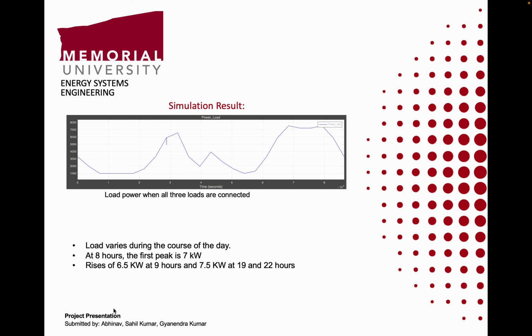Then the active power of the secondary side of the pole mounted transformer is always around 0. The storage battery supplies the insufficient current when the power of the microgrid is insufficient, and absorbs surplus current from the microgrid when its power is surplus to the electric load.